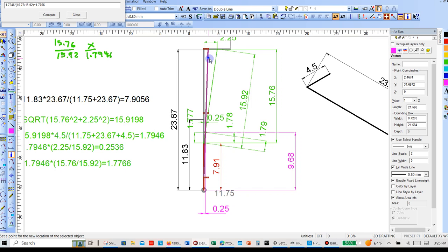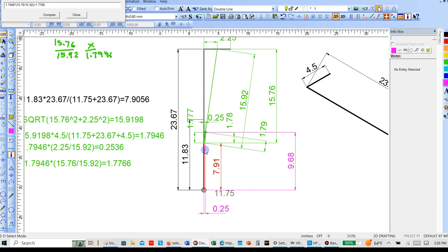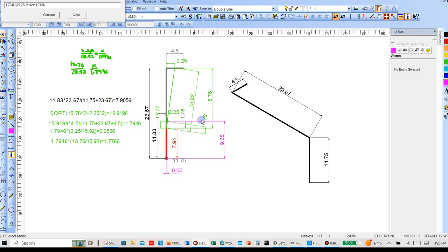So the limitation there is sling length, right? You have to have exactly the right sling lengths, and then they've got to stretch at the same rate, and it's going to be hard to make those match because they're going to be kind of arbitrary. As long as the hook is above this point, it'll be good. So probably what you want to do is run 2 slings. Let's say this was 9.68.